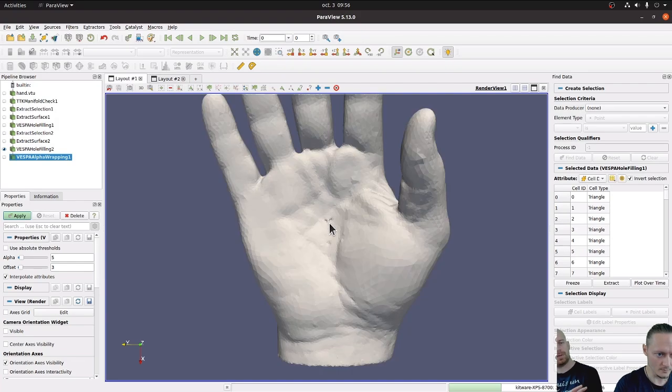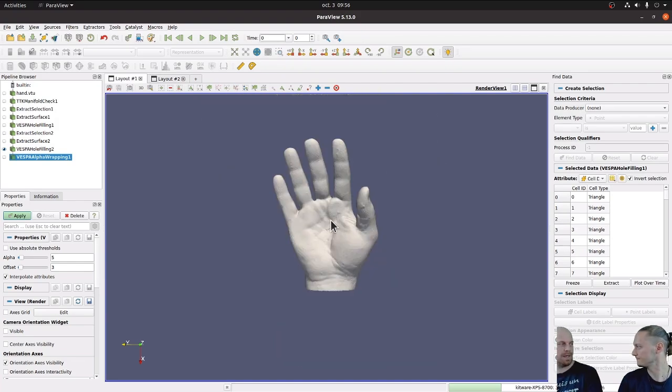So just to make sure I understand, it's a bit similar to Delaunay, just another algorithm to do something similar to what Delaunay does. The alpha wrapping, in some way, yes, but it works really differently, because the way Delaunay works, it's just connecting things which are close enough. Here, the alpha wrapping will basically create a huge sphere, a huge convex hull around your dataset with a given resolution, and then it will try to push on every part of this convex hull to go into your datasets and make the new one as close as you indicated to imitate the shape of the datasets.